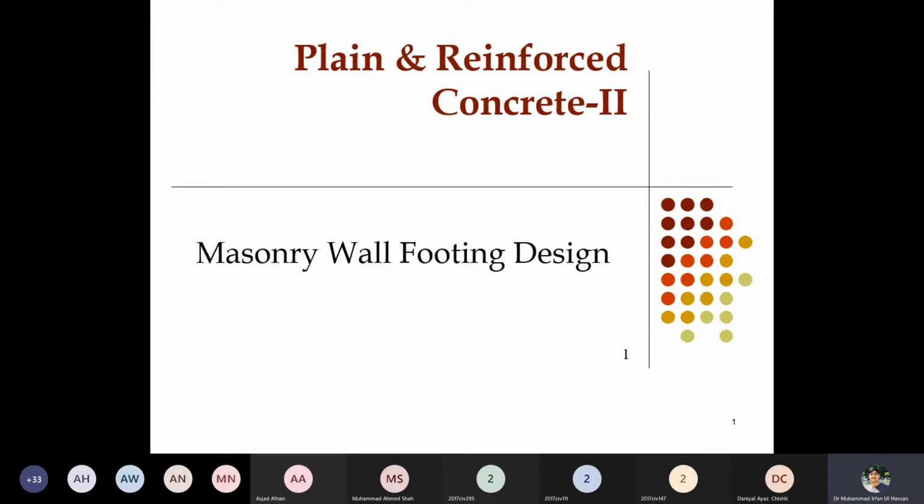the foundations at the base and providing the PCC layer, or if the load is higher, then you can go for the RCC under the bottom of the footing. So this foundation is basically provided in many cases in academic buildings, masonry buildings, in houses, in offices also, and even in RCC buildings where there are no columns, and you have to raise the wall from the base ground floor. In that case, you are going for the masonry or the separate footing.